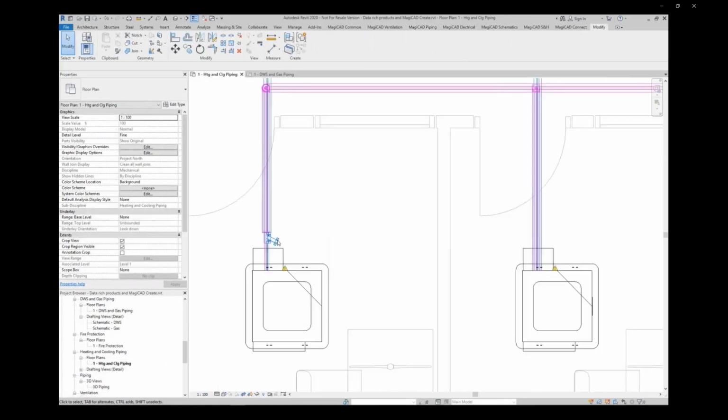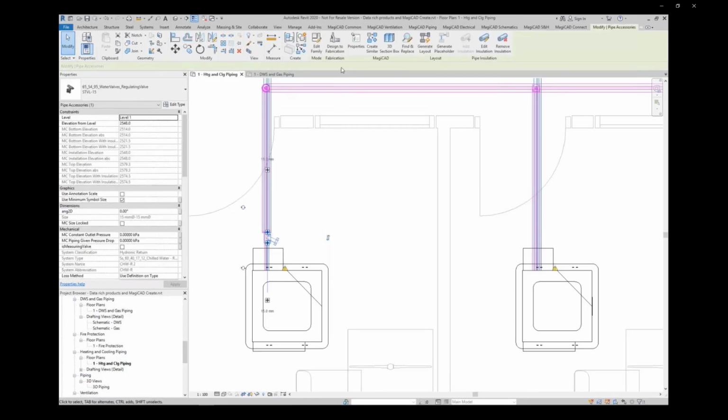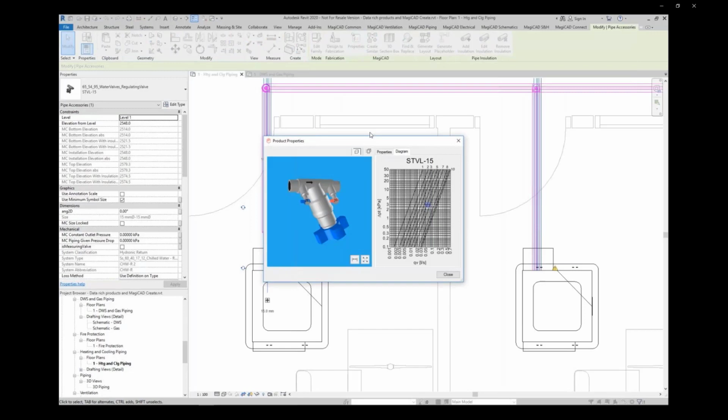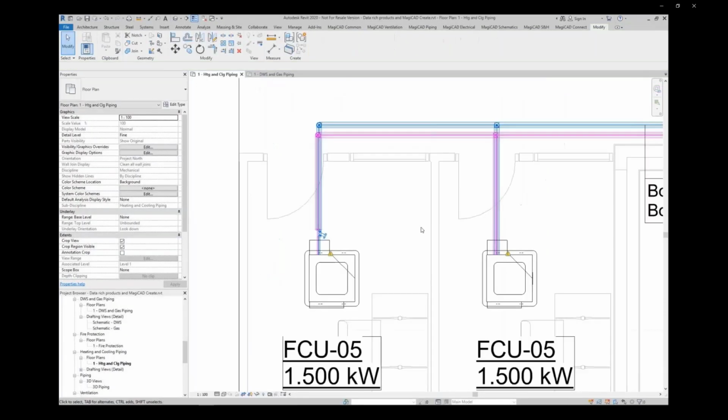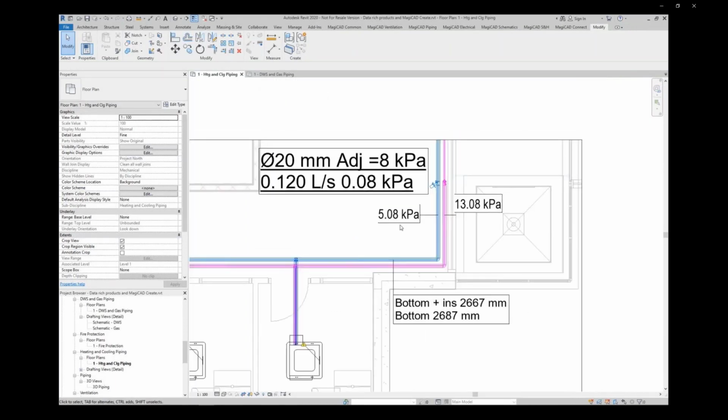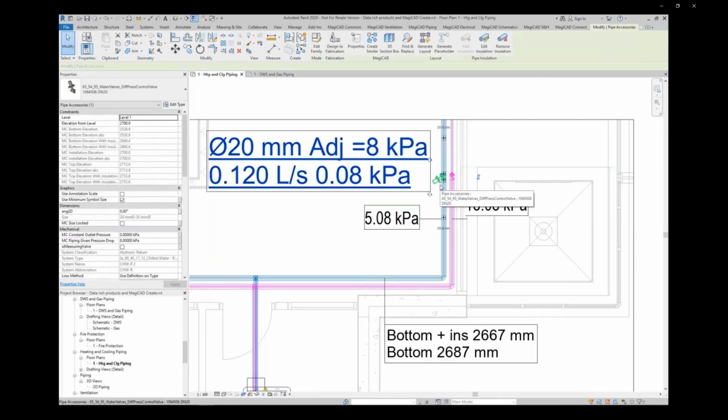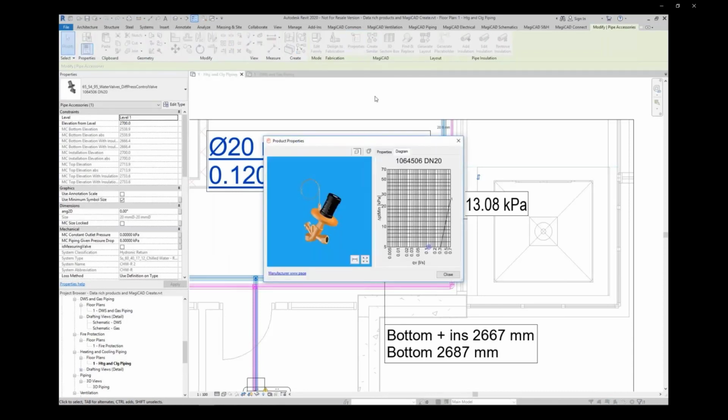And this takes us to the fact that under the umbrella of zone valves, like this one here, we have a regular balancing valve before the fan coil unit, and the differential pressure valve that we just installed. So we have different kinds of valves under the same zone valve category.